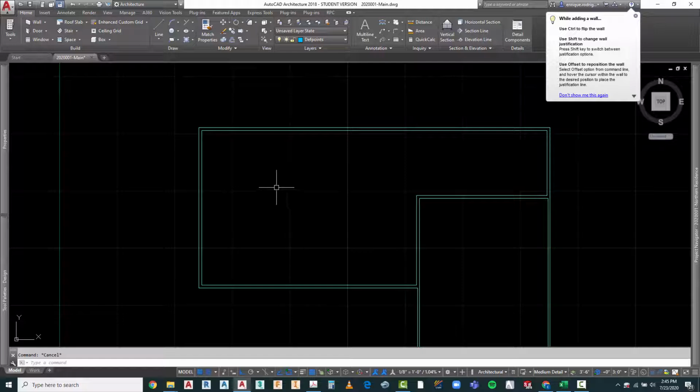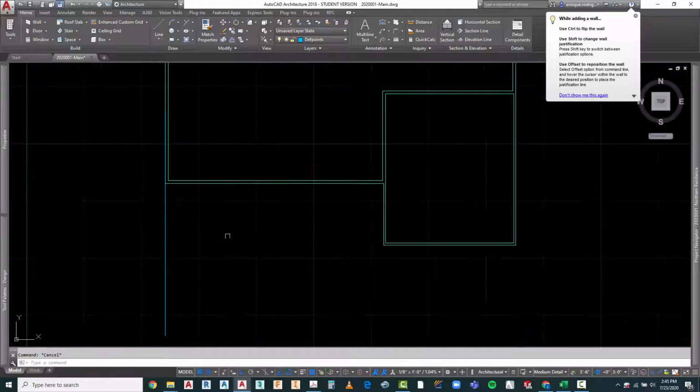So let's go ahead and start working our way. If we take a look at our markup, it gives me the first wall to where the stair is going to be, and I'm going to go back to depth points here. I'm going to draw a line in here. It says that wall is located at 13 foot 5 inches over.